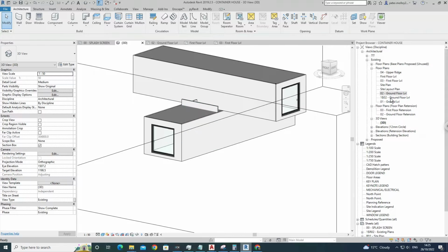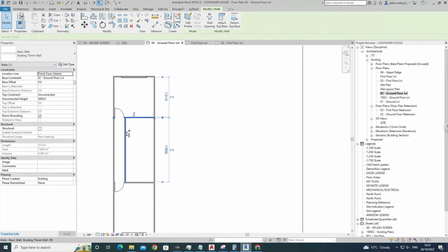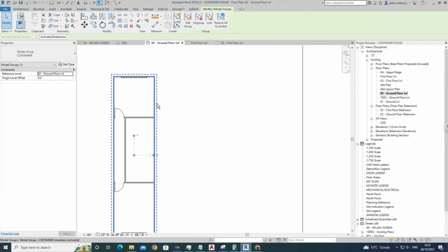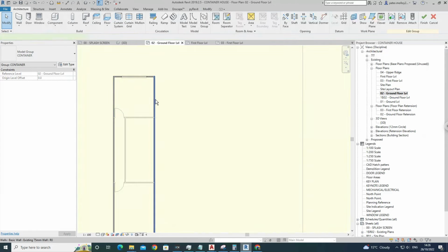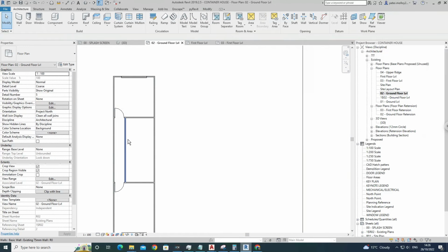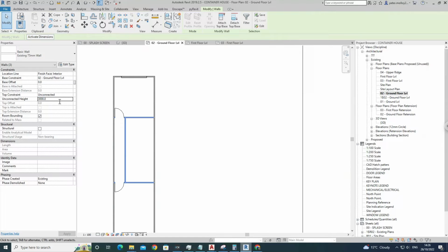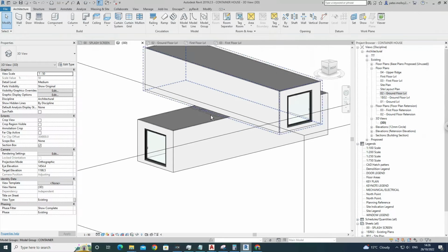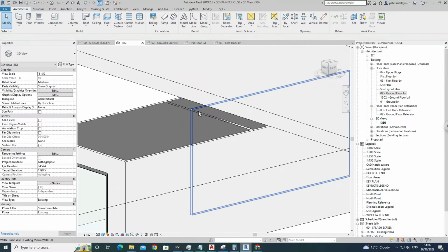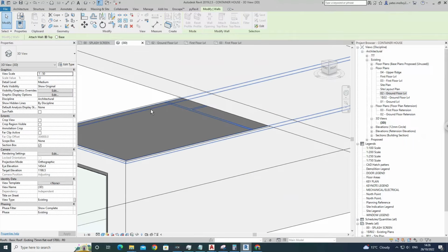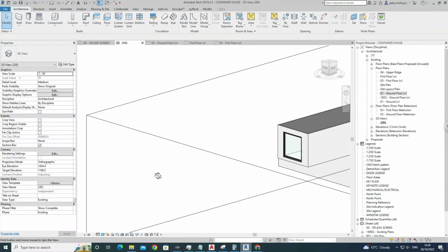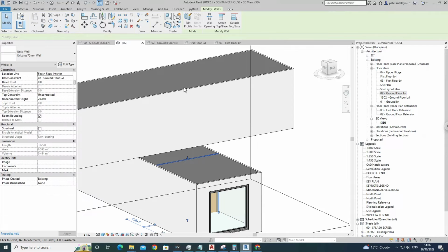Nice. So I'll come back into ground level here, and I'll just put these at, what are these outer walls at again? These are 2600. So I'll put these at 2600. Handy tool as well is just to attach top to base. Attach top to base. Perfect.